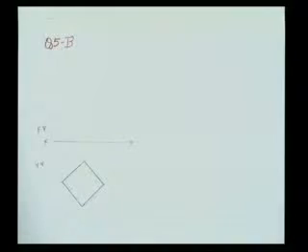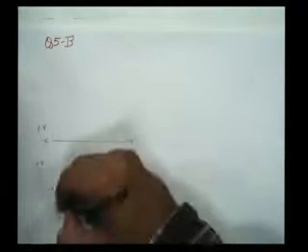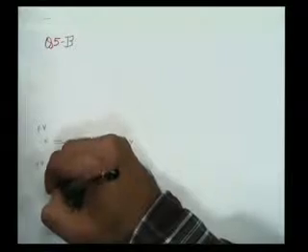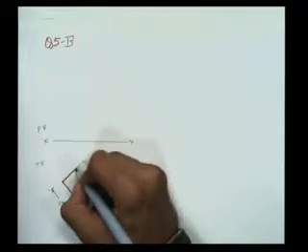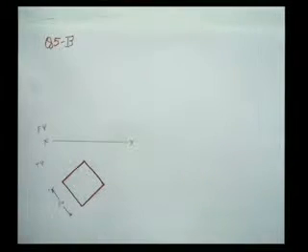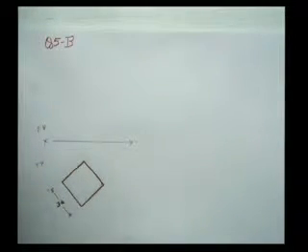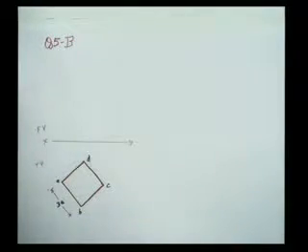Okay, so here we have a square with each side as 30 mm. I'll make it dark using a sketch pen so that it's visible to you. Okay, and this is 30 mm. Right, so now I'll mark the points as A, B, C and D. Thereafter I will sketch off the projections upwards.